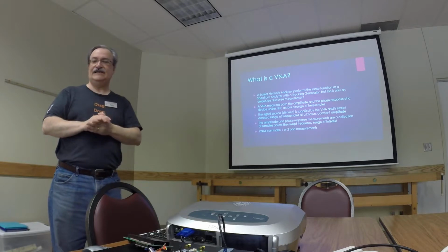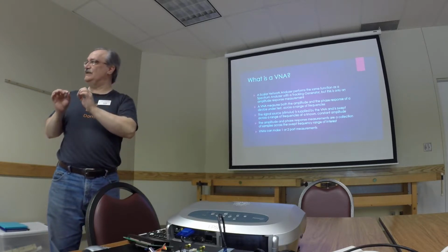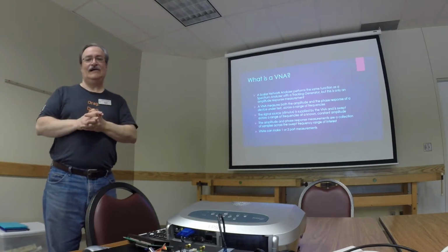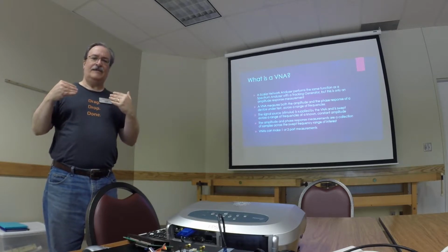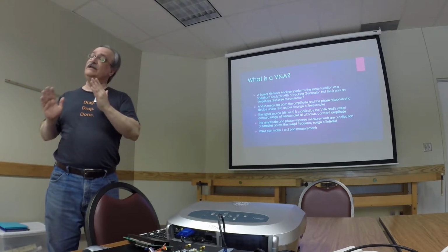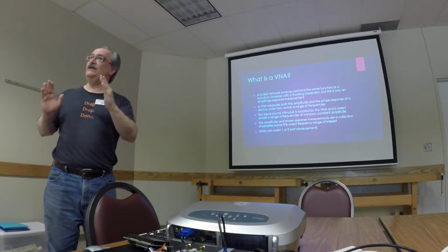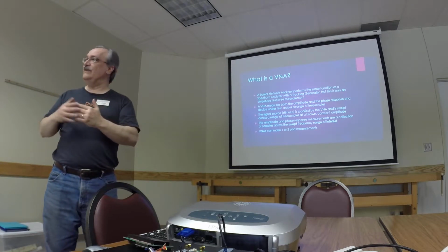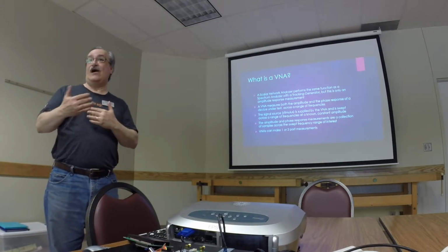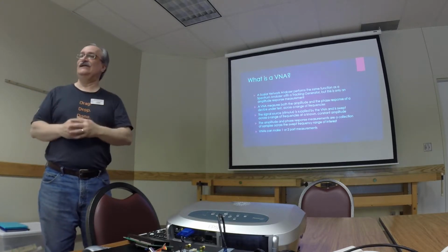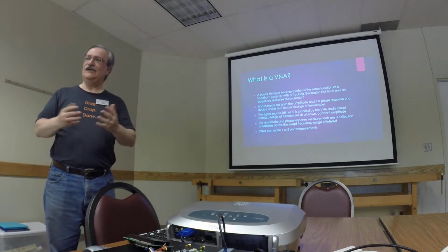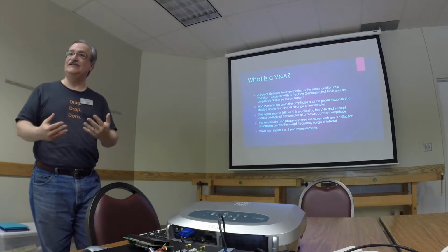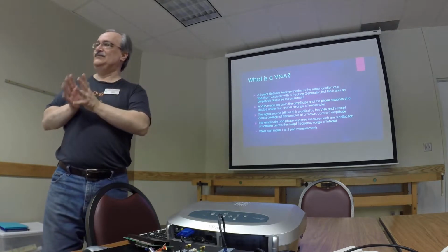For something like this kit, the Analog Devices chip in there that does the phase detecting, which was the most expensive part of the kit, I think it was $42. That's a very specialized chip, but that only covers a range of about 1 to 60 megahertz, okay? If you were to look at an Agilent or an older HP vector network analyzer, that often is in 5 digits cost, sometimes a little bit less if it's broken, you're talking about some very specialized piece of equipment, highly tuned, highly exacting specialized equipment.